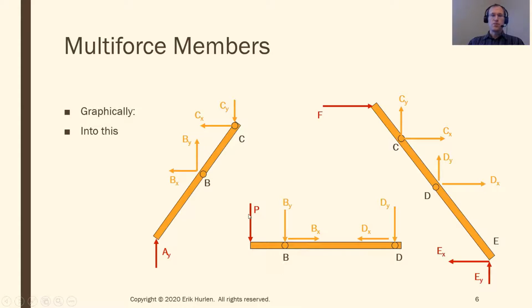So I'm essentially assuming that this horizontal member is pushing it to the left and pulling it up, which means that, equal and opposite, this angled member ABC is pulling down and pushing to the right on this horizontal member BD. So equal and opposite forces at pin B between these 2 members. Similarly, at joint C, I have equal and opposite forces between the 2 members.